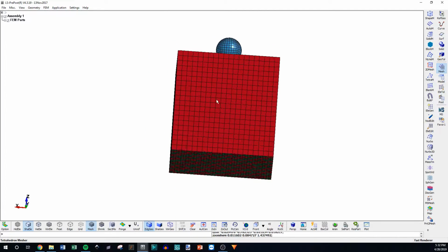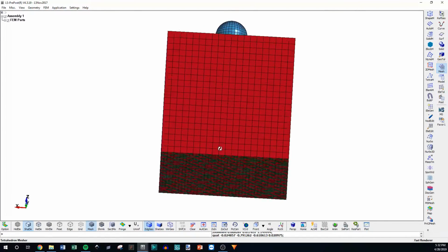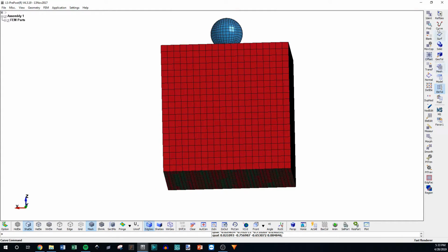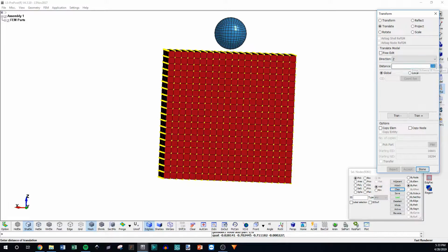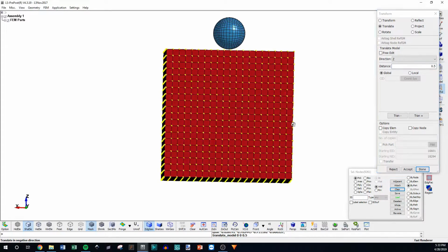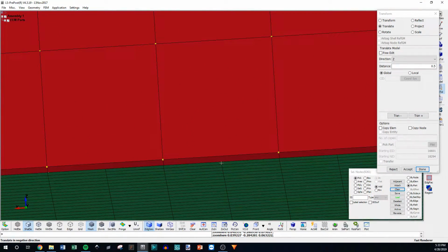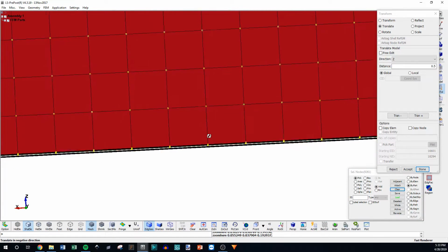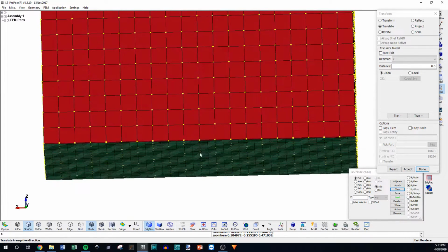And then let's also move the block up 1 millimeter because we're going to make this bottom plate 1 millimeter thick. Actually, I can make it 0.5 up. So we're going to move this block in the Z direction 0.5. It'll make sense later. I'm getting it off of the plate because these two things are going to have a contact with each other. I'm going to end up making this bottom plate 1 millimeter thick, and it's going to extrude the thickness in both directions. So 1 millimeter thick is going to be 0.5 and then 0.5. If we move the block up 0.5, it's going to remove any initial intersections between the block and the plate, but it's going to be close enough so there's not going to be any movement when we simulate it.